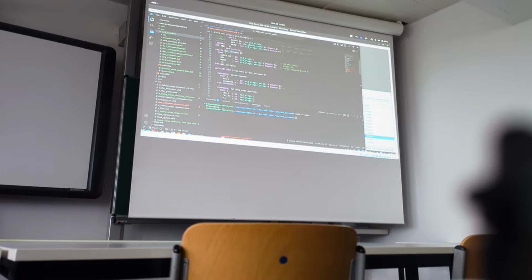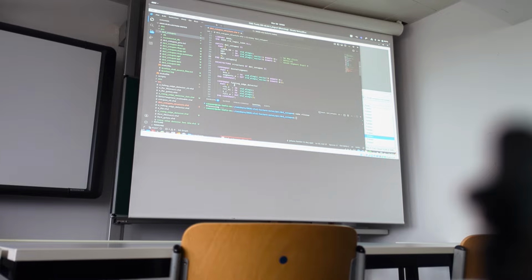The DE1 count up enable uses the clock signal, the key, which is a vector of 2, 1 for the asynchronous reset as mentioned before and 1 for the enable, and the hexadecimal display at the moment. We need to introduce or make visible 2 components. One component is our binary to 7 segment encoder, and the other is our counter.